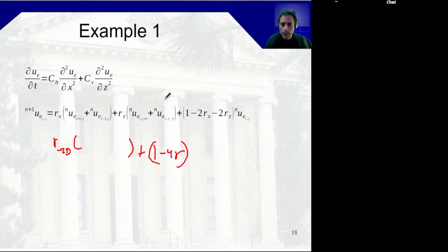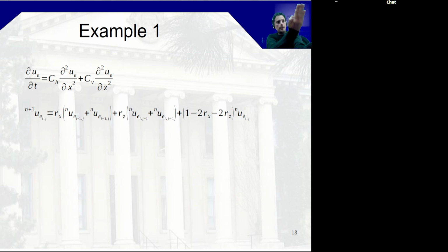So now we saw what a 2D analysis entails. And you remember, a 2D analysis entails that you have things extended to infinity perpendicular to your image. Okay, perpendicular to the screen, it goes to infinity. Or very long anyway. So it's good for strip footings, problems of that sort. But it would not be a good representation of a circular footing or a square footing. For a square footing, you need to go all the way to 3D.